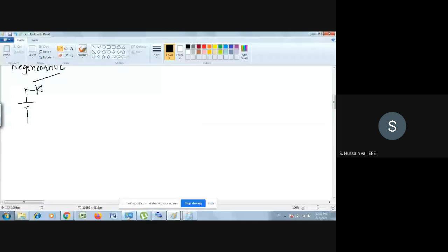See, the circuit does not change. Whatever circuit we are using, only the motor changes here. And what is the main difference between this motor and the previous motor? The main difference is that in place of RA, you will have RA plus RS. That's it. There is no other difference. So circuit wise, there is no difference here. This analysis is very same as the previous one.